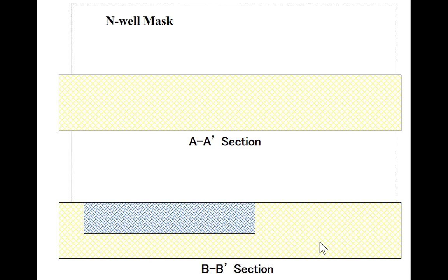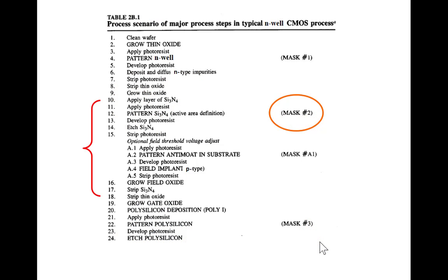Wow. First step in the recipe, the N-well. So here's our N-well. Now, it might be the case that we do a drive-in diffusion here. The impurities don't go that deep when we implant them. Then we typically heat it up and let the impurities go down a ways. So I'm not going to worry about whether they've been driven down yet or not in this presentation.